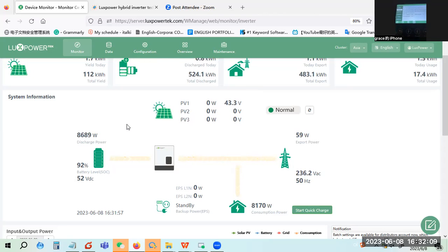and then you go here. You can set charge first, charge priority, and we go to AC charge. We can go to discharge to like force discharge and set the discharge time, and also we can see that we can set on-grid cut-off here 19%. I was just setting that in the monitor system.